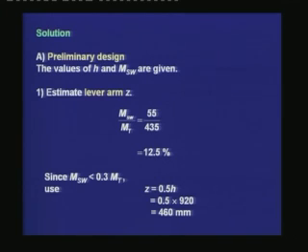We are also given the prestressing at transfer and at service. We know the allowable compressive stress in the concrete at transfer and service. Since this is a type 1 member, the allowable tensile stress is 0. We also know the type of prestressing tendon that we are going to use. The properties of the prestressing tendons will be available from the supplier of the prestressing steel.